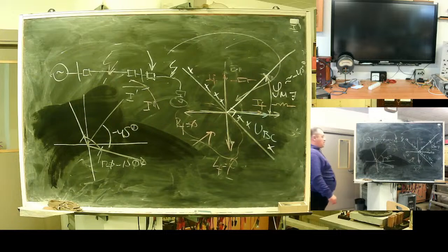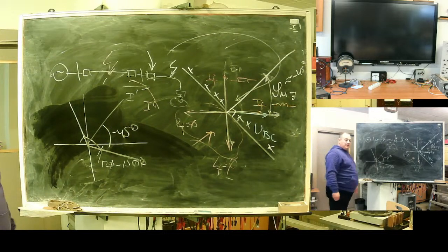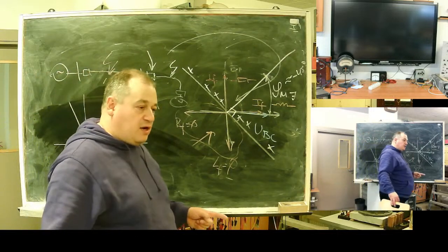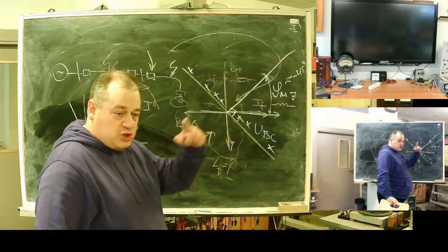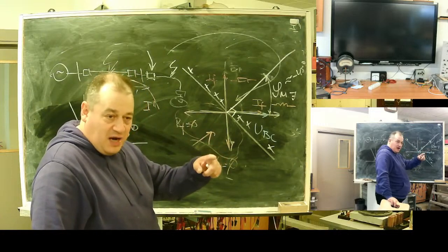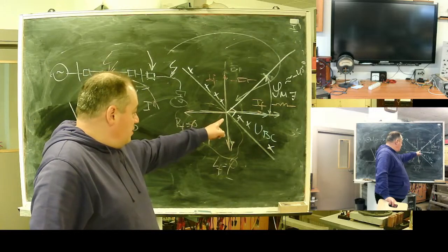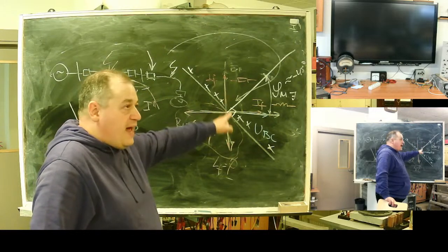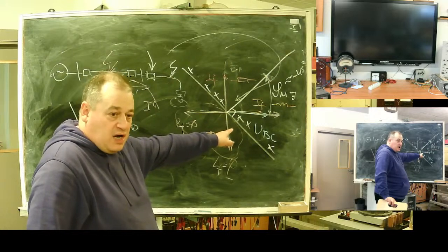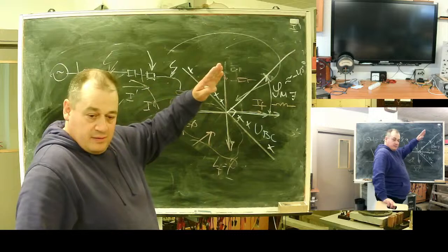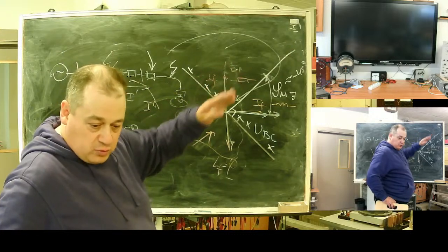From voltage to current. Watch it closely. In some cultures, angle is measured from voltage to current, and in others from current to voltage. Here, in our tradition, angle is from voltage to current. Minus 45 means the current is ahead of voltage.